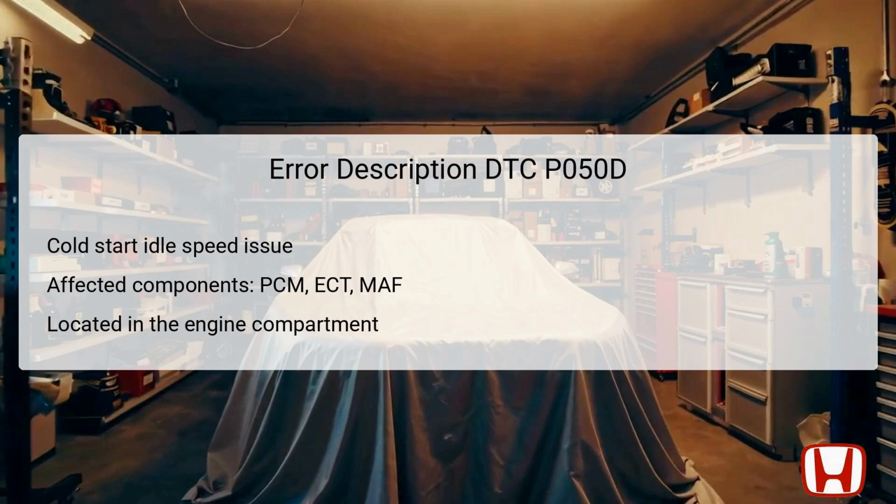These components are located in the engine compartment. The PCM is usually secured in a designated housing, while the ECT sensor is typically positioned near the thermostat housing. When the engine is cold, the PCM adjusts the idle speed based on readings from the ECT and MAF sensors, and any malfunction can disrupt this delicate balance, leading to the P050D code being triggered.